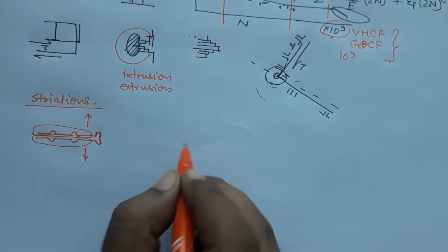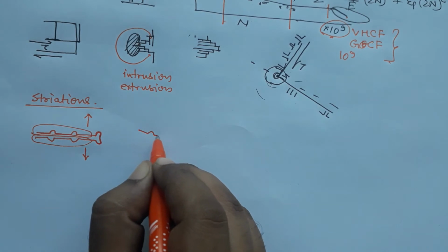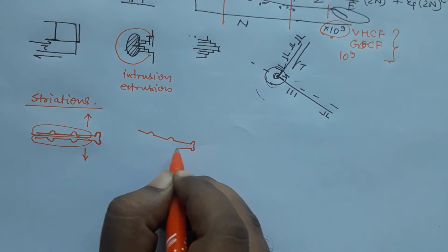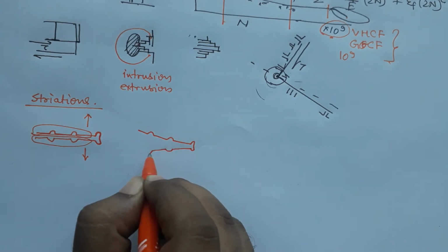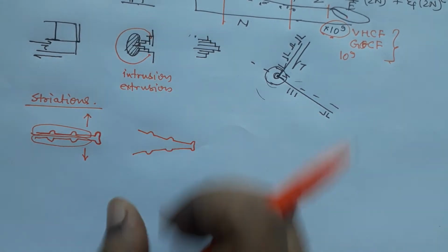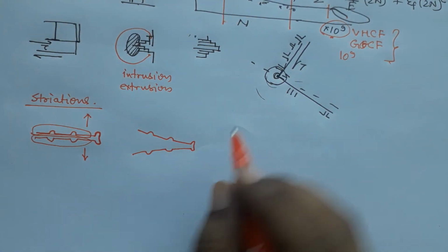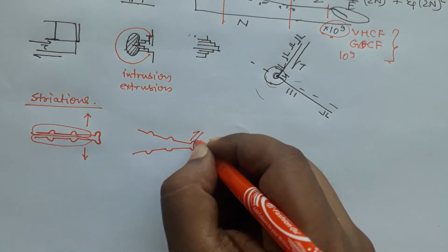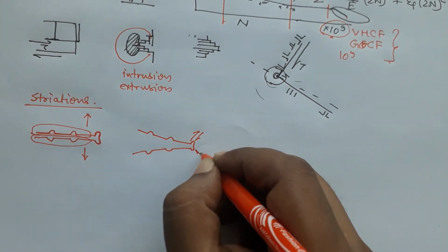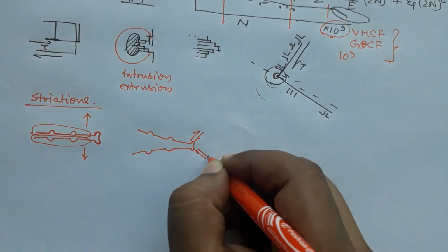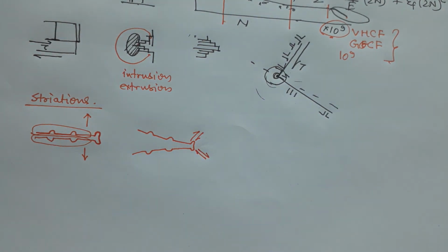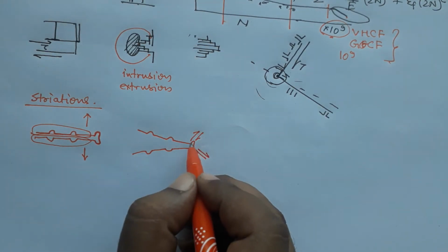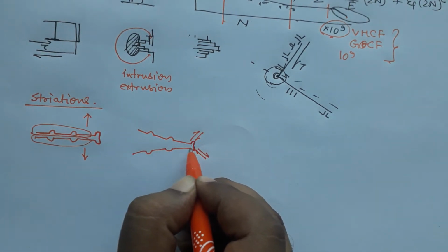So that will open up very easily, and this part which is connected to the material will not open up. So it looks like a hinge now, and here you will have shear stresses, and we know that shear stresses usually happen at an angle close to 45 degrees. So you will have shearing happening in this direction, and therefore I have this kind of opening here.